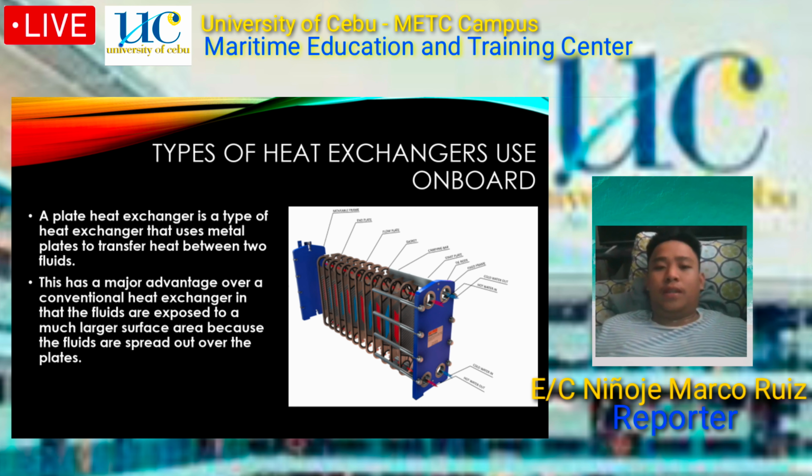The types of heat exchangers used on board. Plate type heat exchanger. A plate heat exchanger is a type of heat exchanger that uses metal plates to transfer heat between two fluids. This has a major advantage over a conventional heat exchanger in that the fluids are exposed to a much larger surface area because the fluids are spread out over the plates.